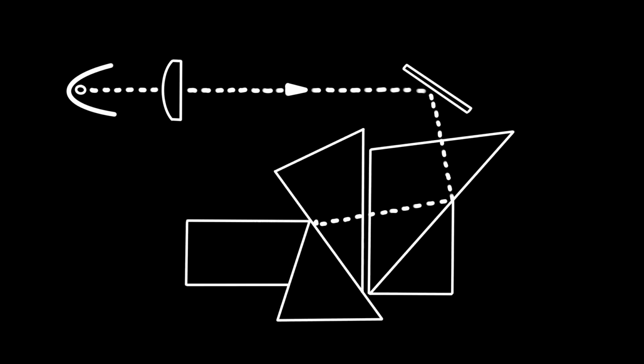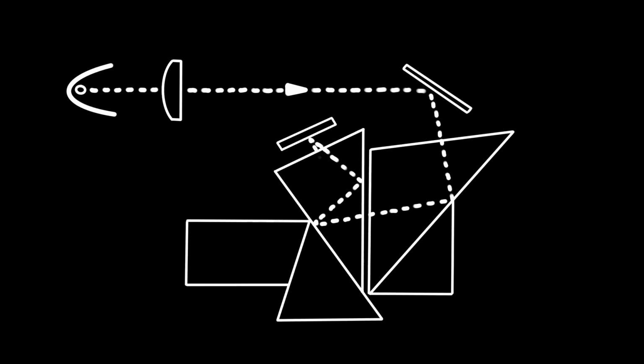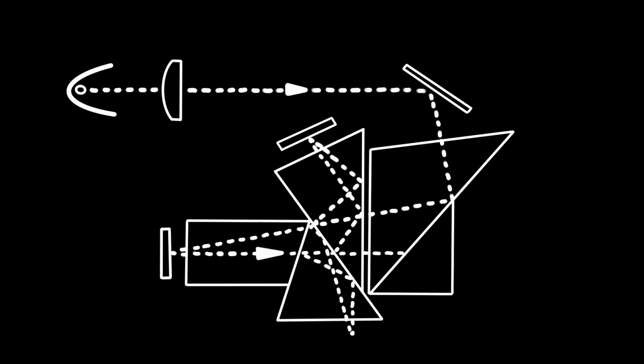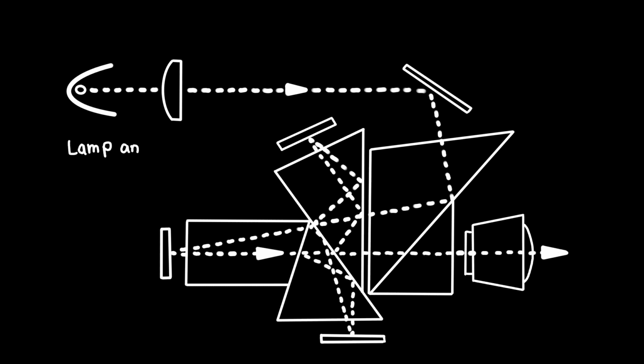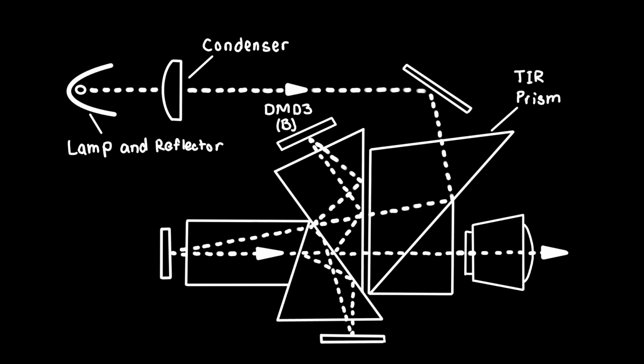From the folding mirror, the light goes through the total internal reflection prism, TIR prism, which consists of the beam splitting prism and individual color prisms, through the DMDs, then all converging back through the TIR and out the lens. DLP has the highest brightness, best video performance and fill factor, best uniformity, and is best for a multiple projector blend application.